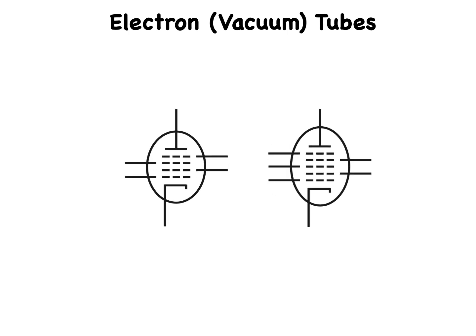In some older radio and television receivers, tubes with 4 or 5 grids were sometimes used. These tubes had 6 and 7 elements, respectively, and were called hexodes and heptodes. These esoteric devices were used mainly for mixing, a process in which 2 RF signals having different frequencies are combined to get new signals at the sum and difference frequencies.